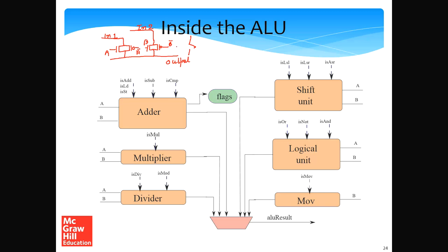Similarly, we can connect 10 other inputs to the output wire, and as long as we ensure that only one of the transmission gates, which is essentially just a single pair of NMOS and PMOS transistors, is enabled, meaning conducting, the output will be equal to that input, and the rest of the inputs will be floating.